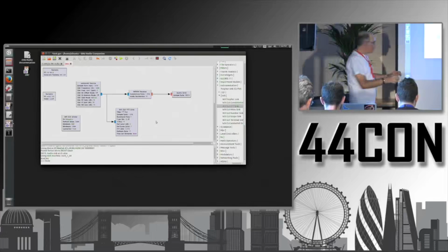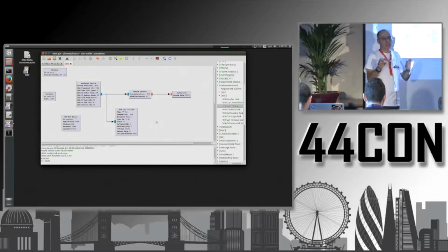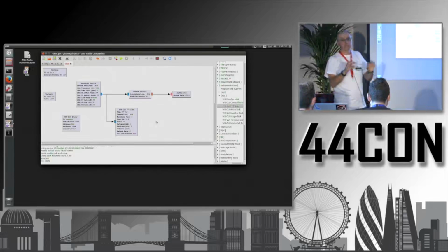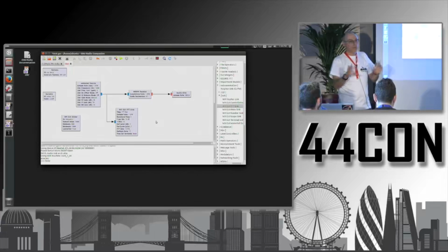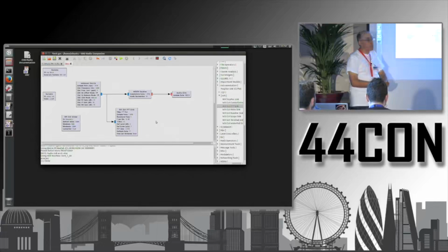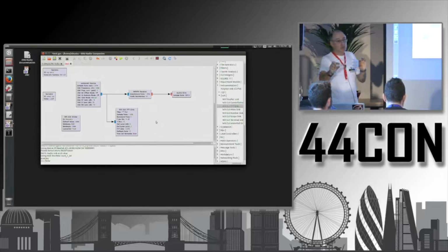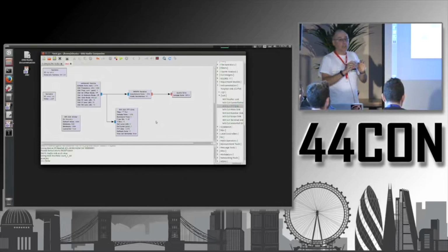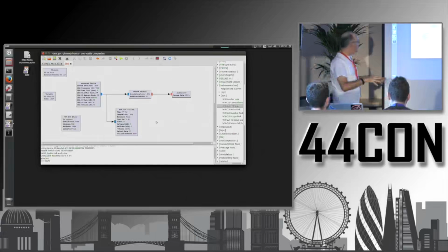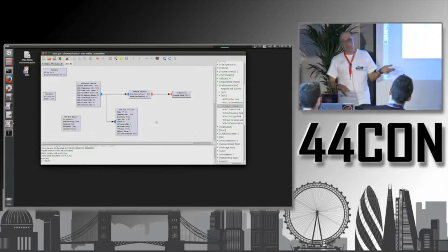If you just put two copper traces on a printed circuit board next to each other, that works fine in a classical electronic environment, but when we are talking about radio frequencies, those two are already creating a very small capacitor. And that very small capacitor can influence the behavior of your circuit because you are working with frequencies that are that high. Okay?